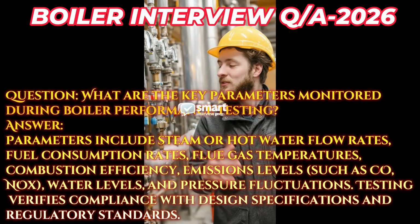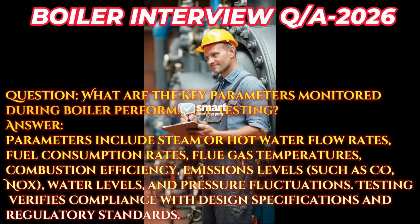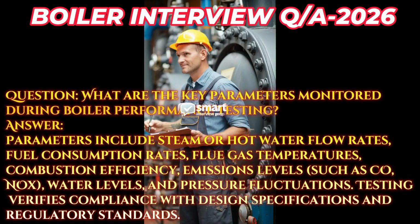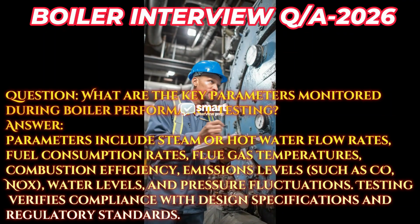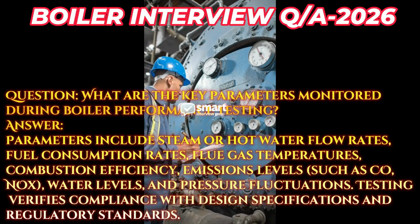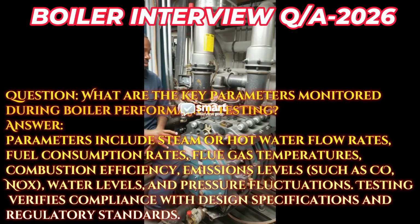Answer: parameters include steam or hot water flow rates, fuel consumption rates, flue gas temperatures, combustion efficiency, emissions levels, such as CO, NOx, water levels, and pressure fluctuations. Testing verifies compliance with design specifications and regulatory standards.